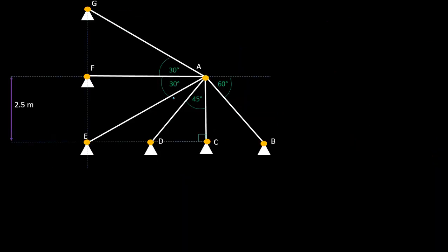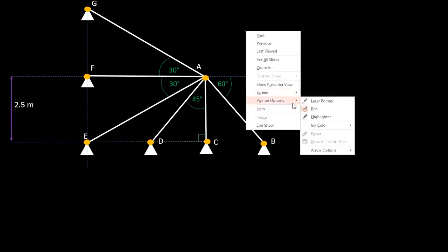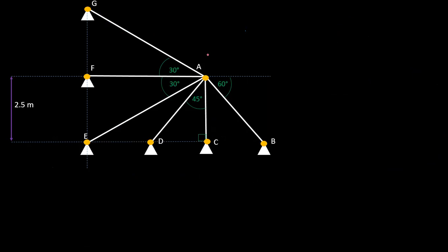So we should find the lengths. We will consider this similarly to the last example in the beams. I take this joint and its displacements. There are 2 displacements right now. In the first beam there was only a rotation, since that was axially rigid. Now you have a displacement in this way and in that way. I will call this my first direction, taking this as the positive direction. This is my second displacement direction, and this is the positive direction.